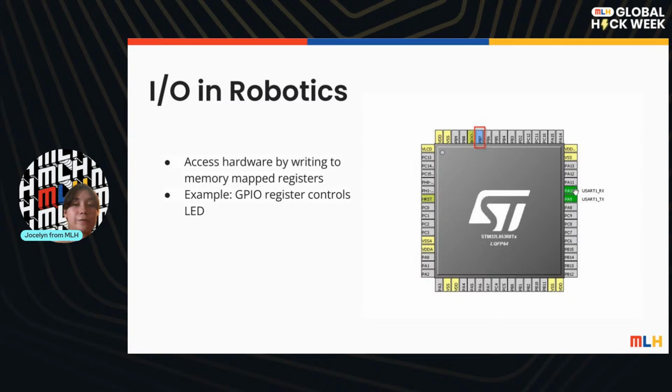So how can you actually configure a pin? It's not just by saying pin A equals port 7. It doesn't work like that. In real life, I know you have worked with these types of microcontrollers before, where you just connect your pin and say that it's going to be connected to 7, and that's it. But how it actually works is you have to configure the bits and how you're going to access that port manually. So all of the configuration is done manually. There are different instructions that you need to follow in order to make your pin work.